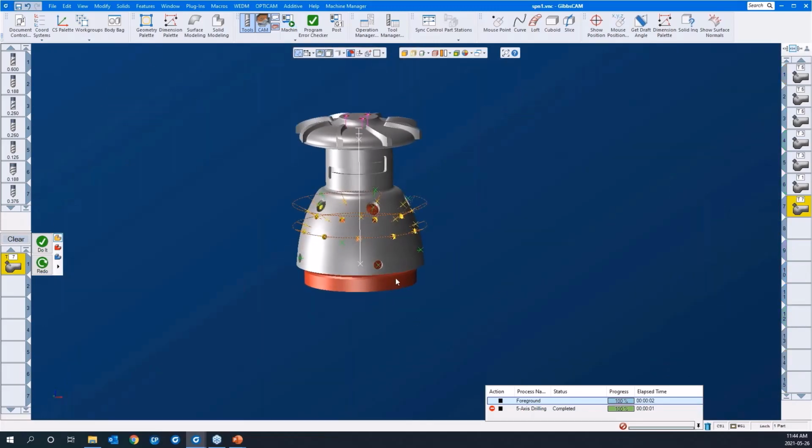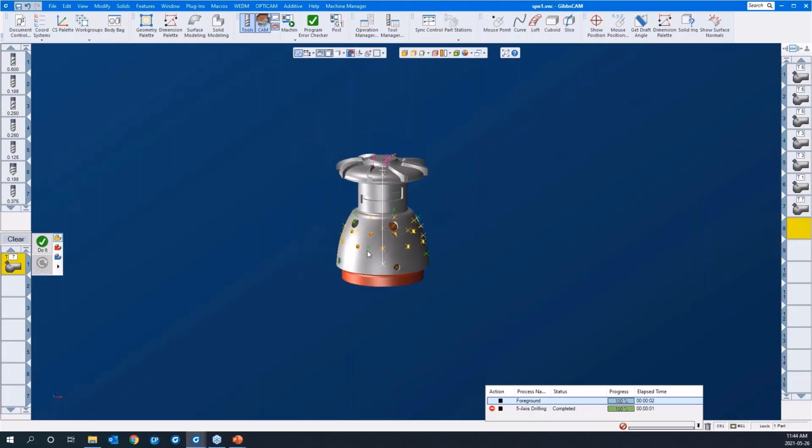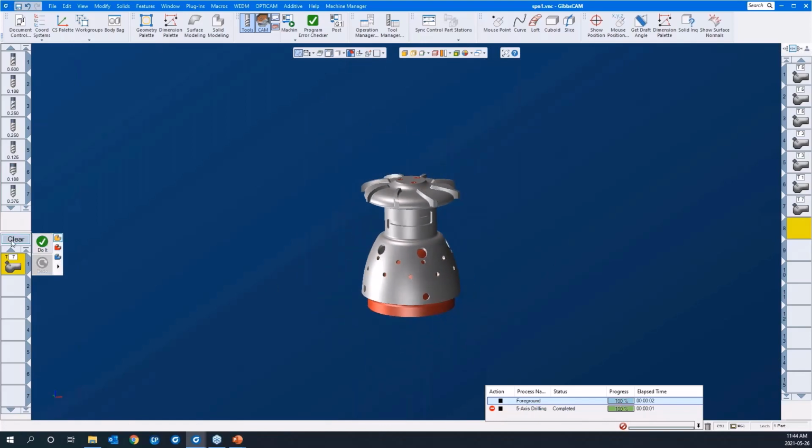Okay, there's a couple other toolpaths I'd like to show you. If you want, you'll keep these whole features, but along the floating taskbar, you can just turn them off so that they're not visible. There's 5-axis deburring, automatic 5-axis deburring in the 5-axis module. Let's just have a look at that. I can pick the entire solid and have it go at it and then exclude edges or what have you.